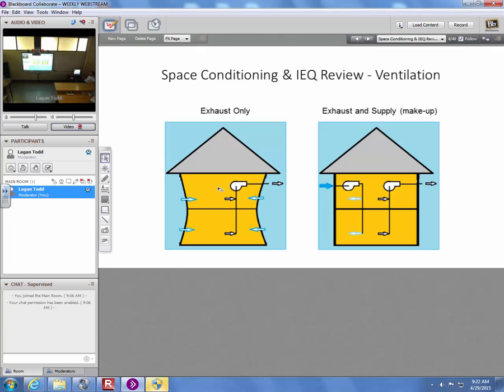The amount of flow rate that fan can move depends on the pressure differential across the fan, and we discussed this when we talked about fan curves. So if you put a 120 CFM fan in, but you have a super tight building envelope, and it's wintertime and you've got all your doors and windows shut, that fan may not be able to draw 120 CFM of outside air. The fan might only be moving 100 or less CFM.